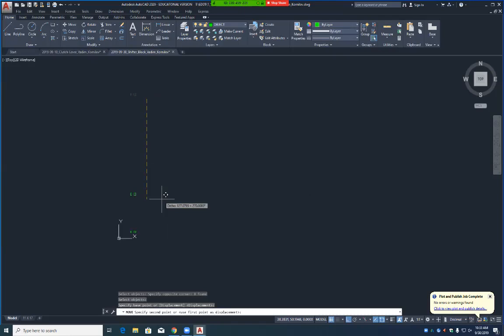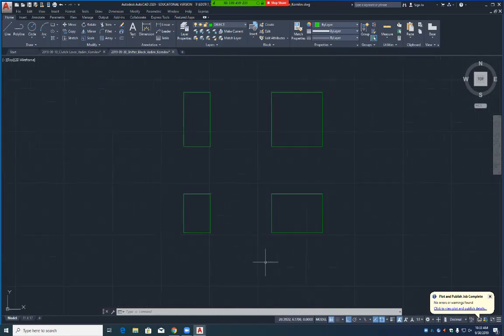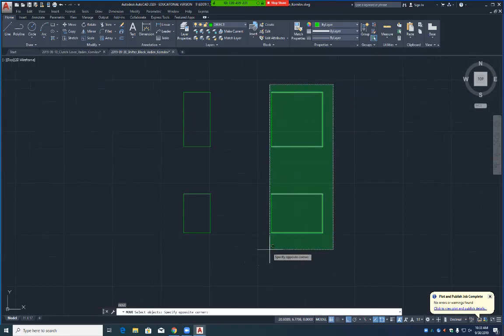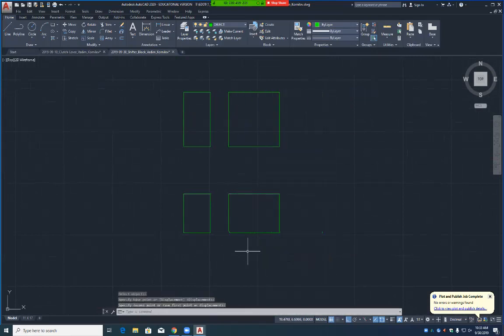And the top down. Click there. Space. Oh, wait, that's 1.88 from the. That's the height. Height is right here. Okay. So space. 1.88. Enter. Pick the bottom, come up. There, you've got your view.